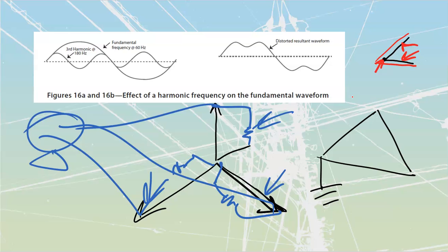They talk about how it gives us issues: circulating currents, and excessive current in the neutral conductor because we're going to try to balance through our neutral if we've got a Y type. We'll get increased neutral to ground voltage and overheating of motors or insulation breakdown that's going to happen if we're pulling more current through one of our lines.